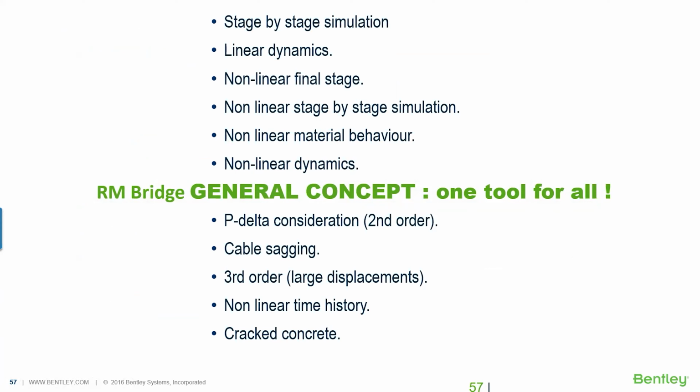We can do general analysis, and we can also do specific analysis, taking into account, for instance, P delta, cable sagging, all that kind of specific thing that often applies to large bridges.